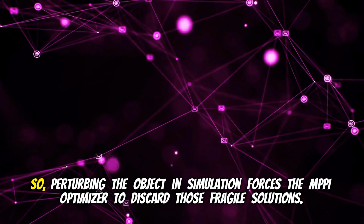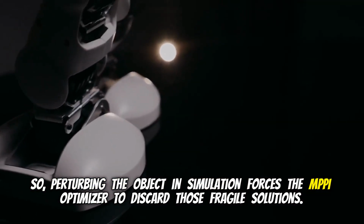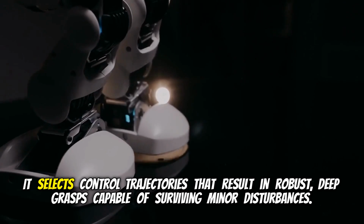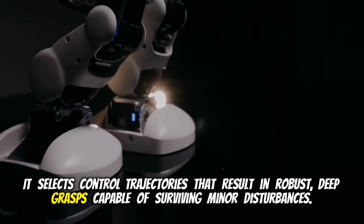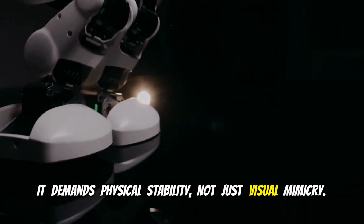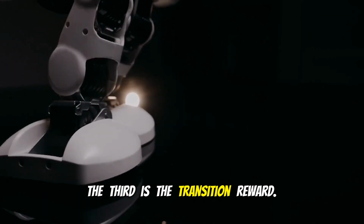Ah, I see. So perturbing the object in simulation forces the MPPI optimizer to discard those fragile solutions. Exactly. It selects control trajectories that result in robust, deep grasps capable of surviving minor disturbances. It demands physical stability, not just visual mimicry. I love that. And the third innovation? The third is the transition reward.